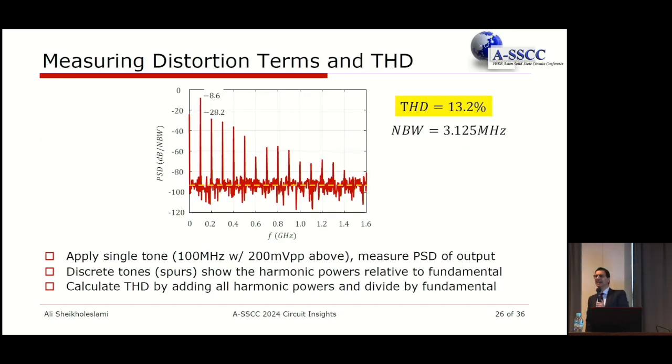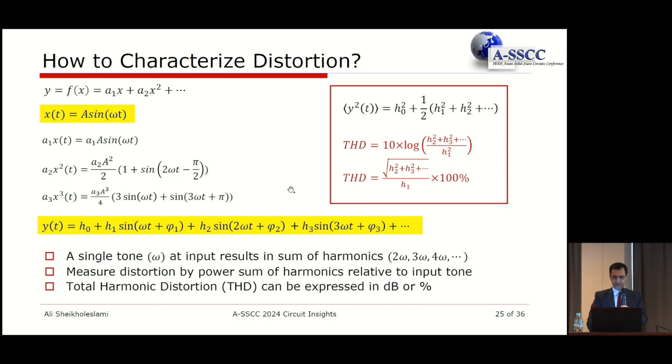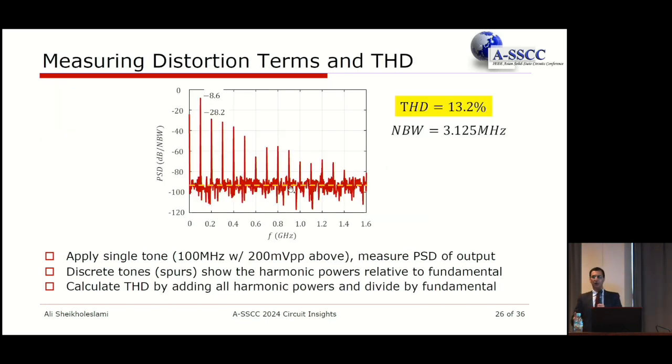Now, let's take that output signal I mentioned on the previous slide, this y of t, and feed it to a spectrum analyzer, or simply find the FFT and see how that looks. This is the power spectral density of that signal. Interestingly, there's some DC value that shows up. We said we can eliminate it, but it does appear in our circuit.